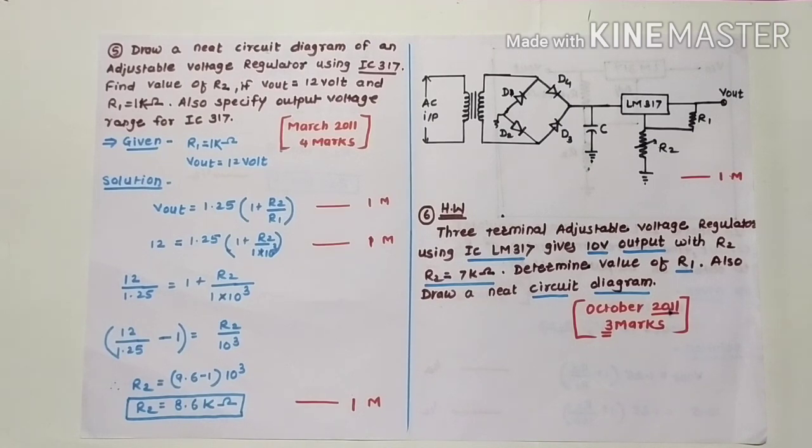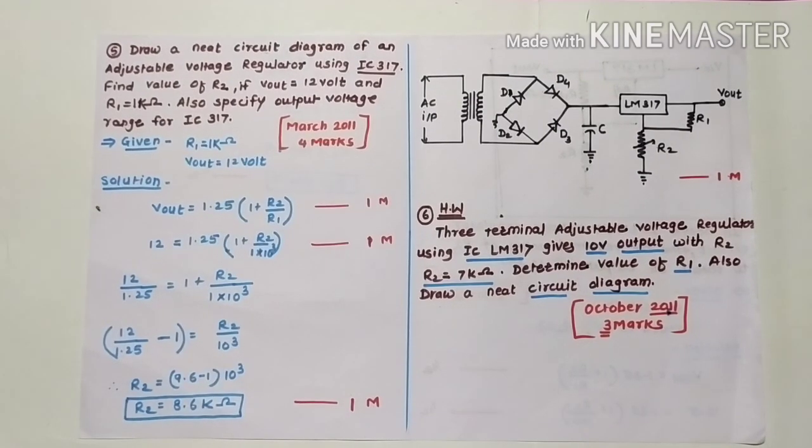Then to overcome some drawbacks, there is the next voltage regulator, the transistorized voltage regulator. Again, to overcome the drawback in the transistorized voltage regulator, there is a current limiting transistorized voltage regulator with the help of transistor T3. Then next is the IC LM317. This is a 3-pin voltage regulator with inbuilt thermal shutdown, current limiting action and heat sink capacity.